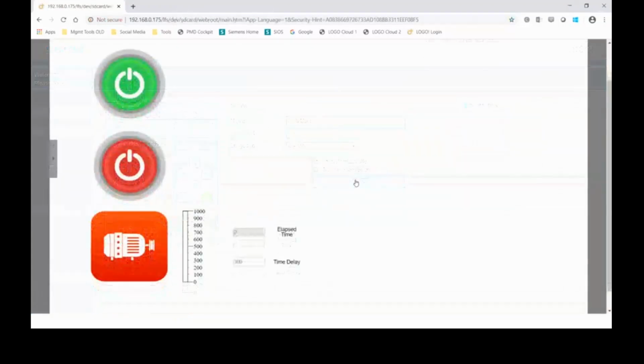And here you can see now I've got my live connection from the web page down on the logo. I can click my start button and you can see the timer value increasing through the bar chart and then the status of my motor change. I can then press my stop button and stop that, which resets the timer. And then remember we assigned the delay set point, so I can increase this. I'll put, I don't know, something like 750, so that would be 7.5 seconds.